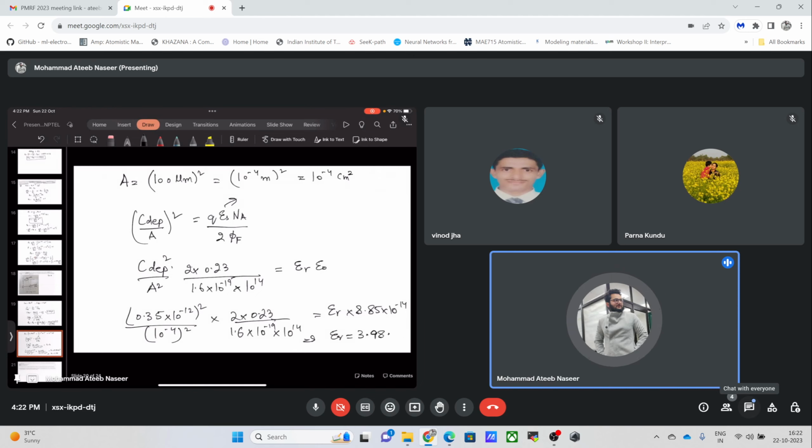and then the resistance will simply be given by the gate bias dependent expression, which is mu n C ox W by L times (VGS minus VTH). VTH is the threshold voltage. From this we can find the value of this resistor.